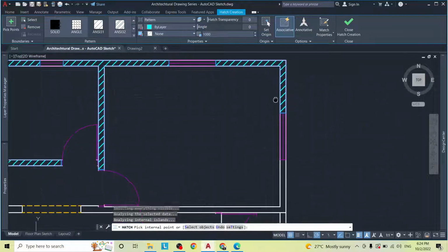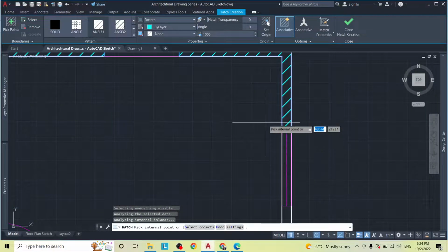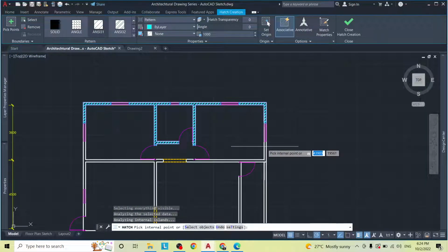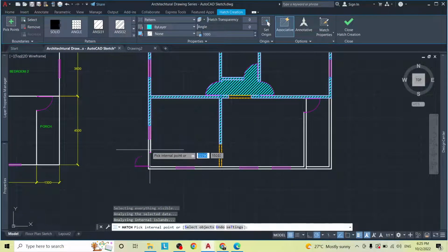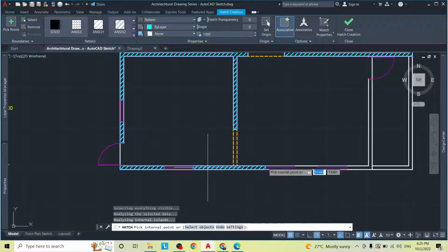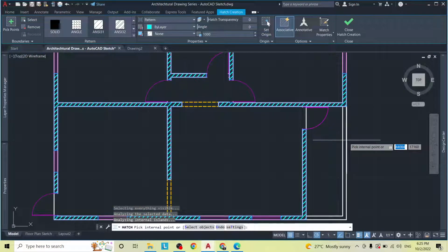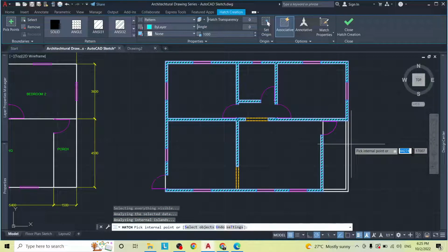All right. So we notice it didn't come all the way around because the window line stopped it in its tracks right there. So we're going to put these hatch lines around all the windows and doors in our drawings. And down here and down here and down there, right there. Excellent. This is not a cut. Remember, this is the top of our balusters, so we don't put hatch lines on top of that.